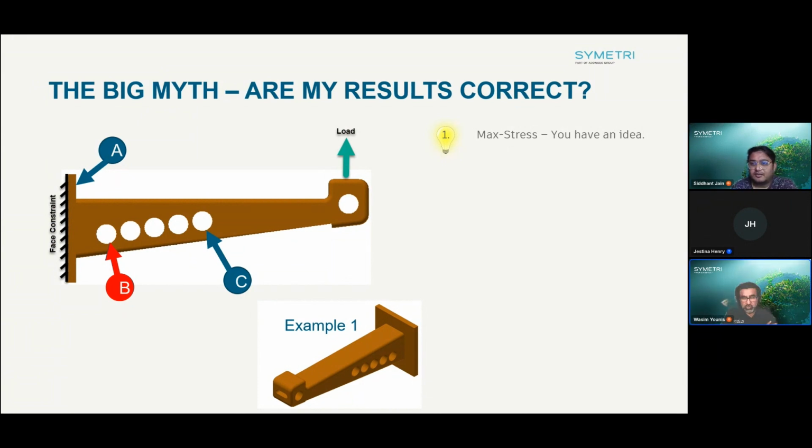Okay, just a bit of a tip. I should have said this before, guys: everything I'm saying here is my personal opinion. A good idea is that you probably get the highest stress nearer the fixing points. Now C is fine, but that's a lot of distance away from the fixing point. When that tries to bend upwards, because there is the least amount of material here, and that's closer to the constraints, that is what I believe is the high stress. And obviously one way to find out, guys, is when you run the analysis.